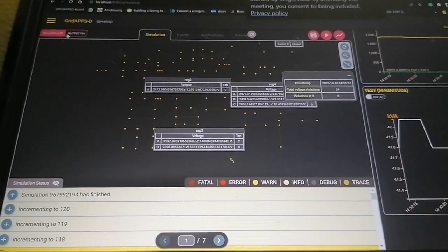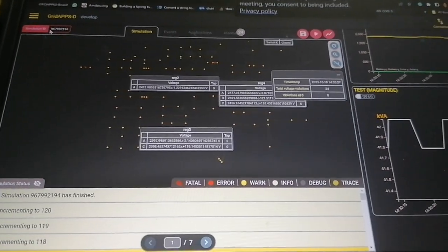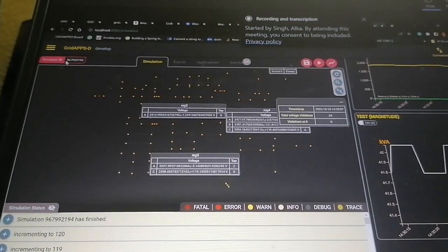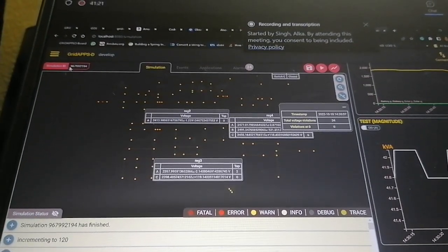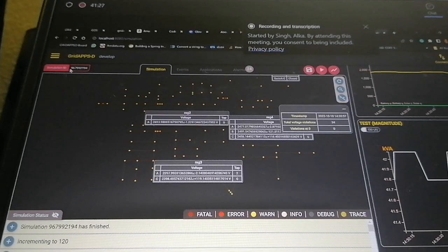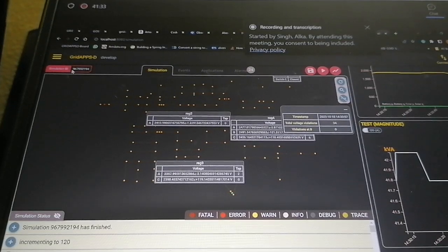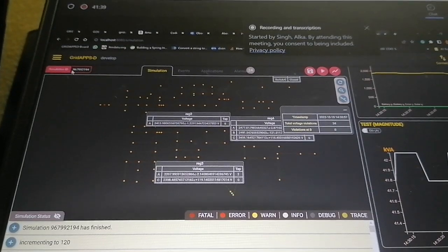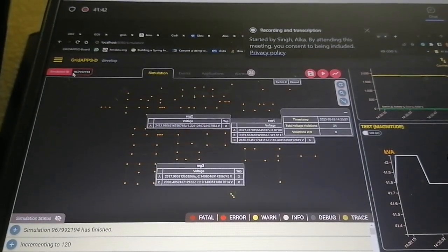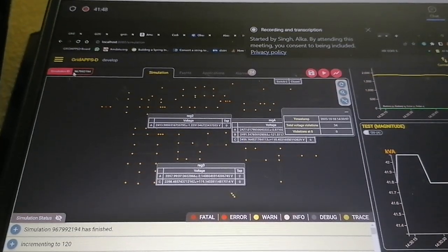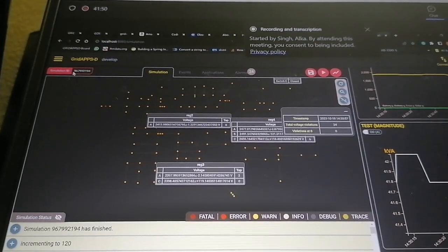So you have two simulators and you want to co-simulate. Is that the case? One on the distribution side and one on the building side. Yeah. Okay, for that purpose, not specifically one distribution, one building, but the Ochre simulator that I was talking about before, their use case was they wanted to run the distribution system in GridLAB-D, but run the houses in Ochre. Ochre only simulates houses, and they wanted GridLAB-D to simulate everything else. So in that case, as I mentioned before, we are using Helix as a co-simulator. That's the whole purpose of using Helix.